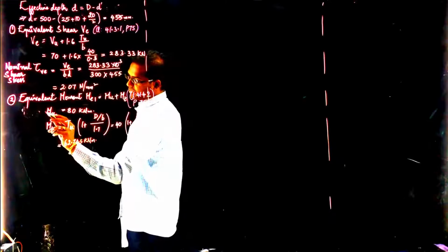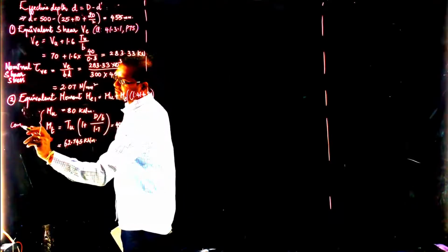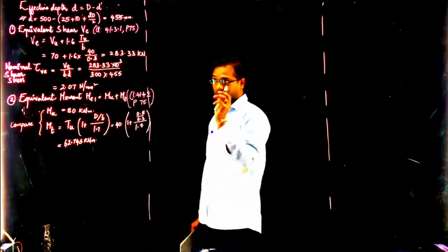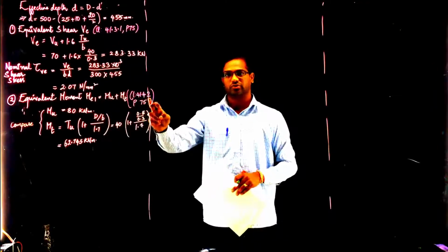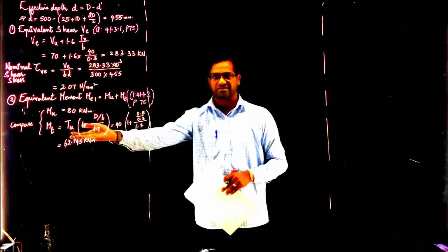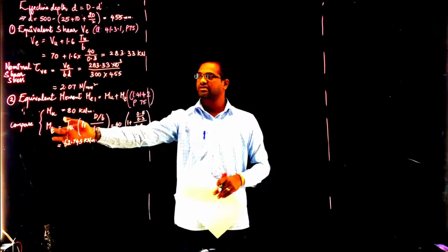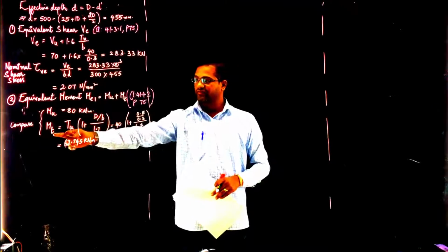Now you need to compare these two in the subsequent clause, because in the same clause 41.4.2, if you read after this equation, if MT is greater than MU, then you need to calculate MU2. I repeat,